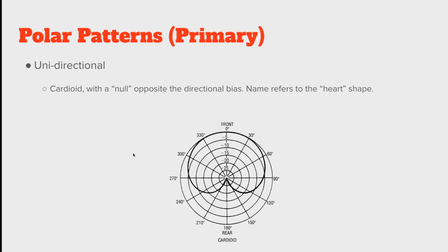We can contrast that with this slide, which shows a unidirectional microphone. It's only going to respond to sound from one direction. Here, as we begin to move off axis from the microphone, we find that the signal again starts to attenuate, but rather than dipping to a null at 90 degrees, this microphone type, which we call a cardioid, goes to a null at 180 degrees.